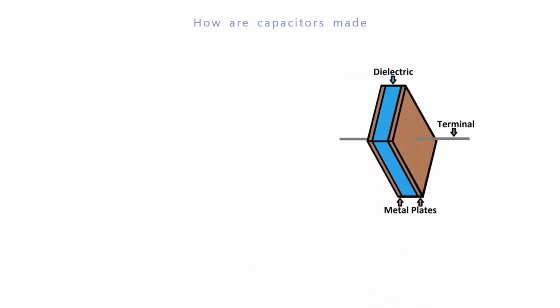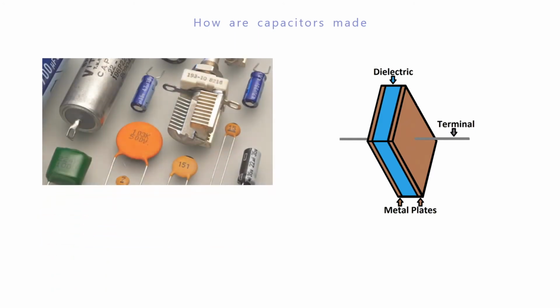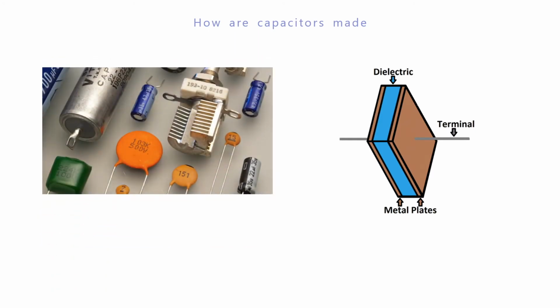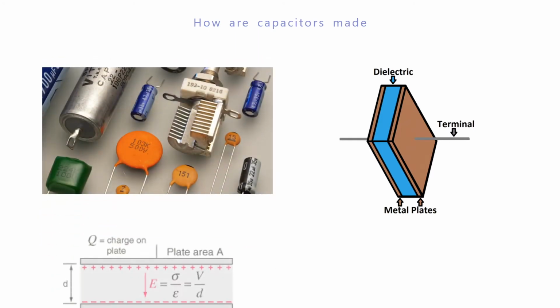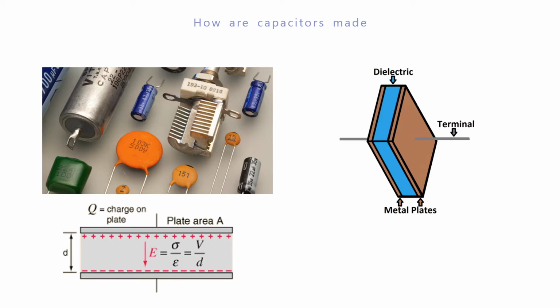The capacitance of a capacitor is dependent on how it's constructed. More capacitance requires a larger capacitor. Plates with more overlapping surface area provide more capacitance, while more distance between the plates means less capacitance. The material of the dielectric even has an effect on how many farads a capacitor has.